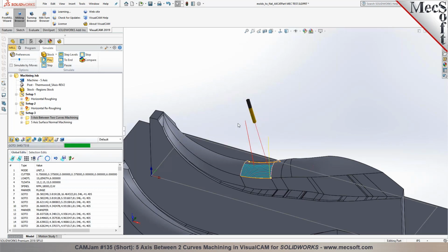Right. So my question is, with the flat end mill, as it's traversing what would be a negative curve, like the inside of a bowl, which is along the tool path right now, it's knowing that the center point of the flat end mill has to be off the actual mold line, and it's using the actual square corner of that diameter to actually remove material to the correct size? Yes, sir. Okay.